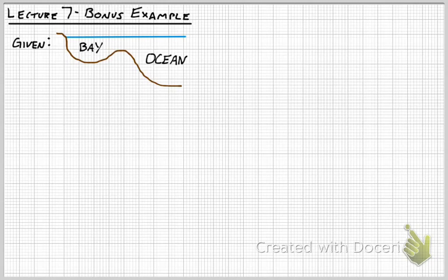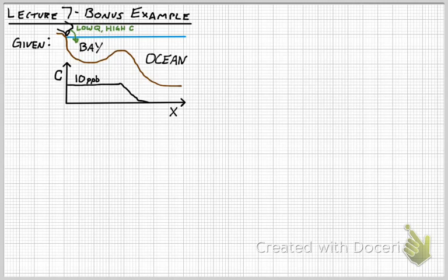Notice that the bay has no inflows of surface water to it. So flow through from the bay is not a process that we'll consider here. However, in our bay, we've noticed that we've got a concentration of 10 parts per billion of a particular pollutant. Now, because we don't have any visible inflows here, we're going to assume that pollutant comes from a relatively low discharge but high concentration outfall. So a very concentrated release of that pollutant into our well-mixed bay.